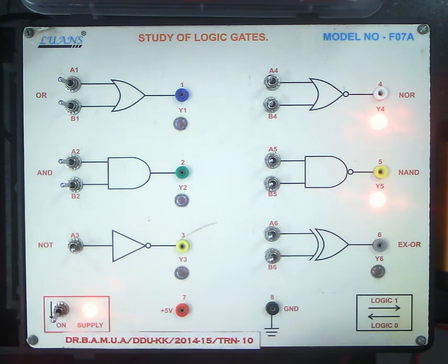Remember one thing, that whenever we are talking of a digital circuit, a high, theoretically it is definitely 5 volt, but actually in a TTL circuit, any voltage which has a value of more than 3 volt is considered to be high. And in case of low logic, it should be 0.8 volt. Any signal below 0.8 volt should be considered as low. Many texts also write 1.8 volt, but please consider this to be 0.8 volt.